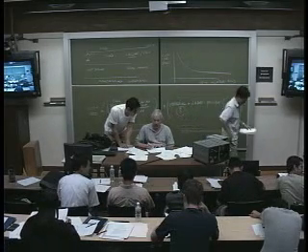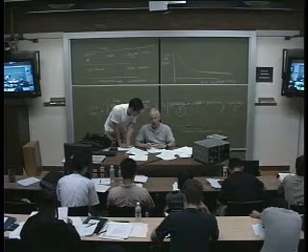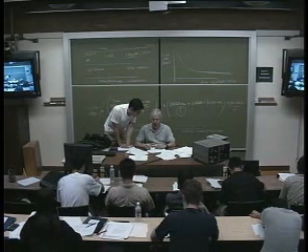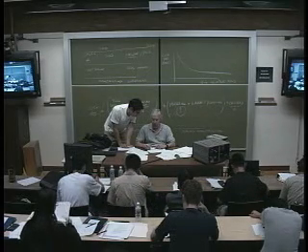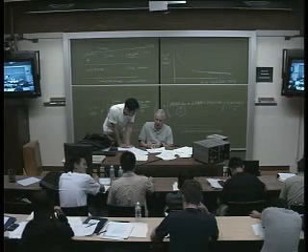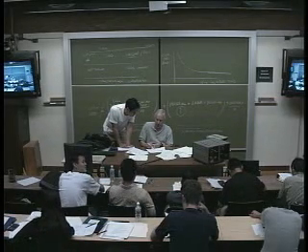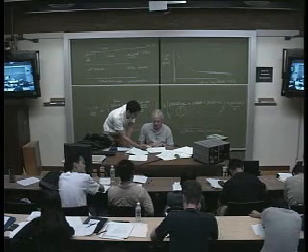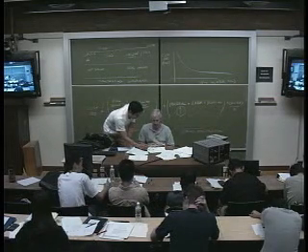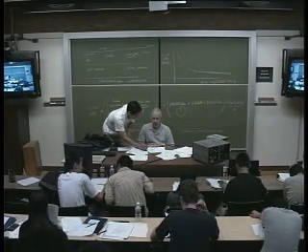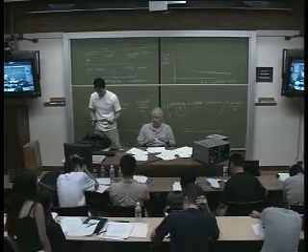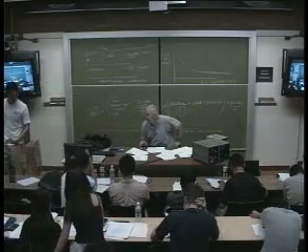Well, looking into a diode connected transistor, the resistance actually is what's set by 1 over GM. But actually not really, because this current equals this current no matter what. The current through here is set by VGS of M3. So if I look into here and change this voltage, I change VGS of this, and that's what sets the current I see here. So M5 doesn't do anything? So this whole thing's resistance is still 1 over GM3? Yes. Oh, wow. Because remember, the current in and the current out of M5 is the same.